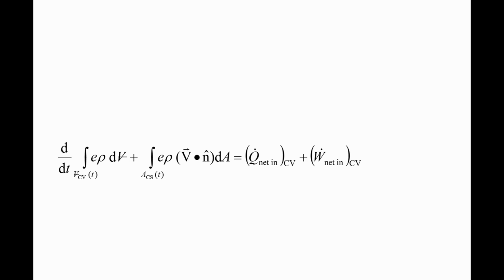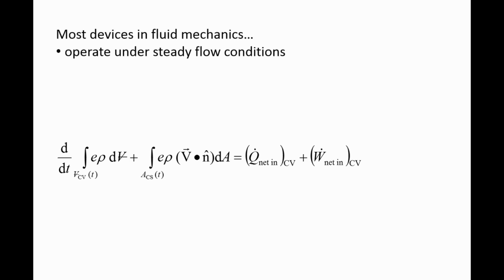We can simplify this equation by recognizing that most devices studied in fluid mechanics operate under steady flow conditions, which means the amount of energy in the device is constant in time. The first term in the conservation of energy equation, which contains a time derivative, becomes 0. Additionally, most devices do not deform significantly, which removes the time dependence on the limits of integration. We will now examine the remaining terms.